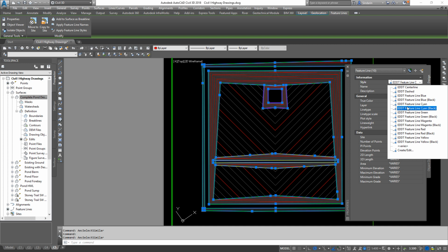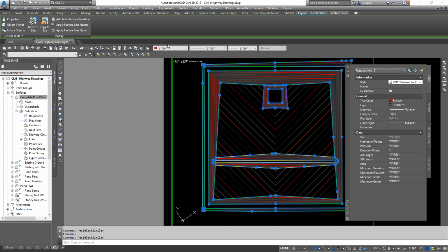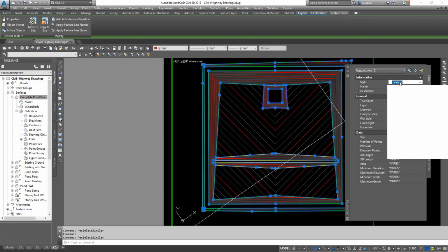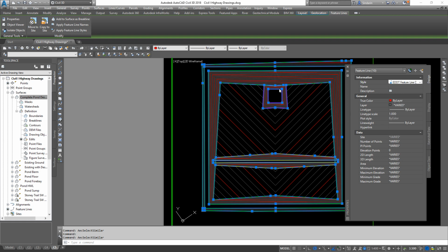And if you remember from the color chart, colors increase in thickness from 1 to 8 in our CTB file. So let's go look at colors and pick, let's make them all cyan. So this is kind of midpoint. I believe it prints about 0.35. So we'll make them cyan black.